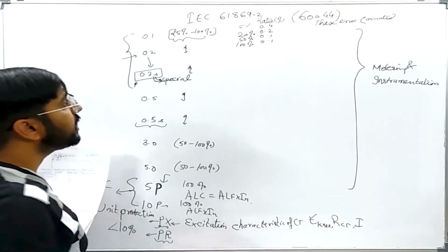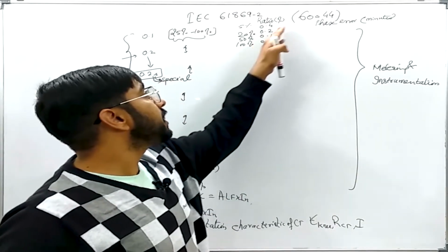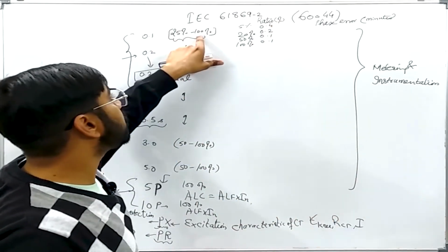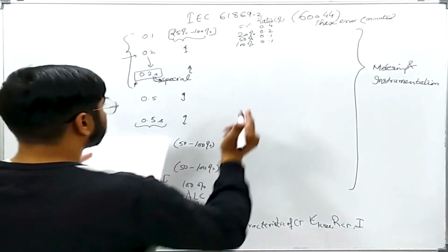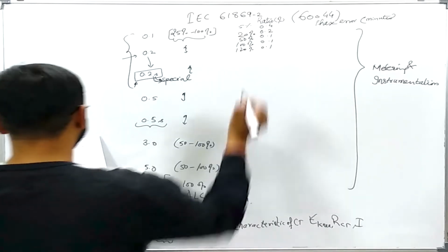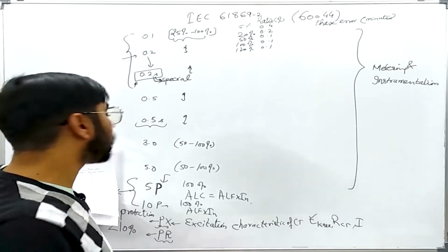Okay, so you see that if the current is lower than the threshold, then even then the CT will be having higher error. Okay, that's why this 25% to 100% has come. Also for 120% it will be having 0.1 only. For normal overloads usually we take 20% overload.